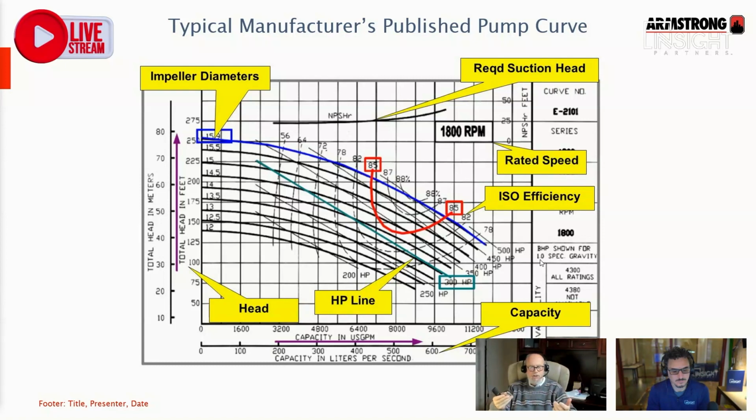We also have the same issue in the data center world, where we're starting to see more and more single phase and two phase immersion cooling systems, where the servers are actually sitting in a tank of liquid. That liquid is a dielectric heat transfer fluid. Yes, we can pump it. It's not a big deal. We may do some different things depending on the fluid, like changing pump seals, but we can pump it.